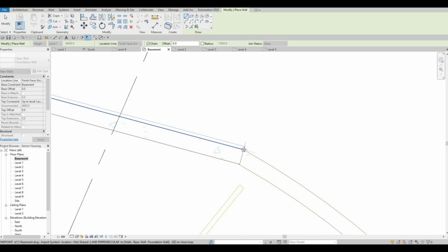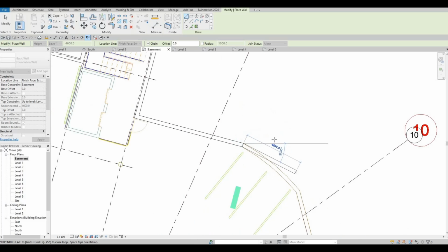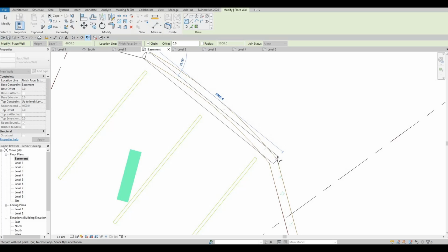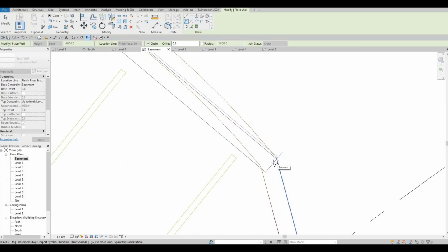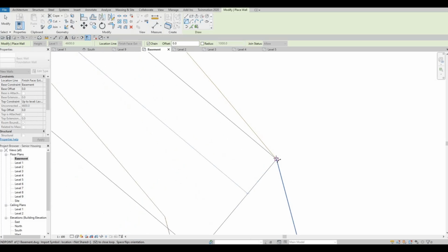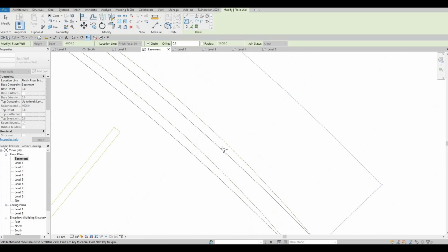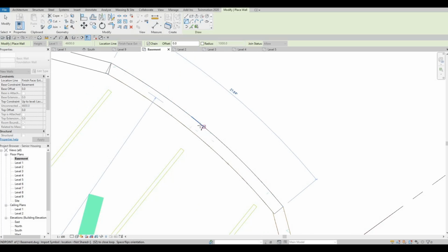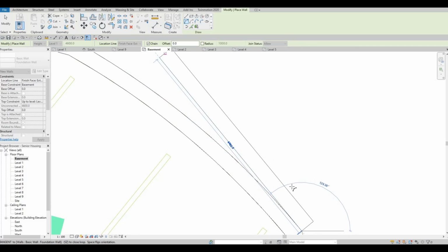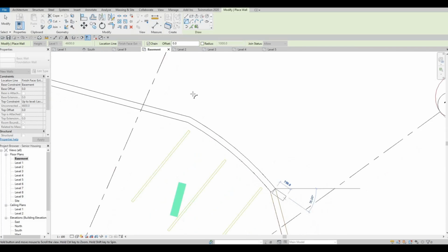And then here, I will stop here and then do a curve. So radius arc, I will go here at the other end as well. You can see the arc and then the line as well here. And then after that, we just need to click again somewhere in the midpoint. So look for a triangle that will be considered as the midpoint of this wall curve.